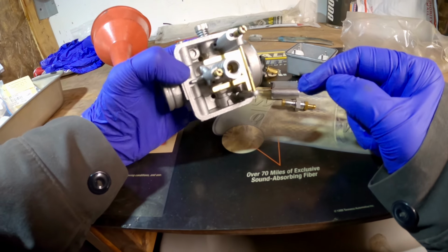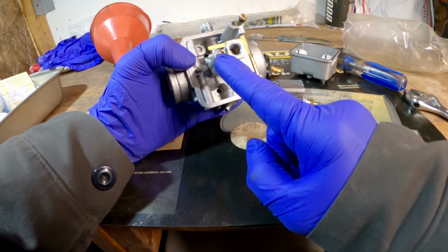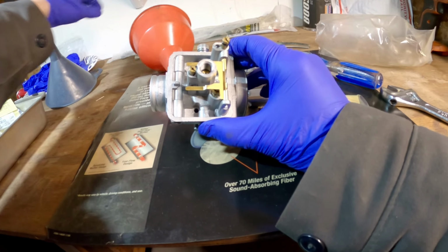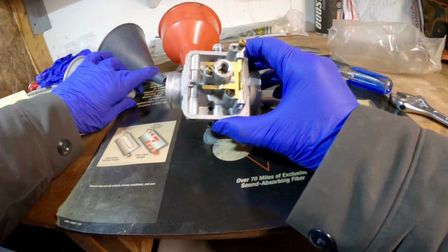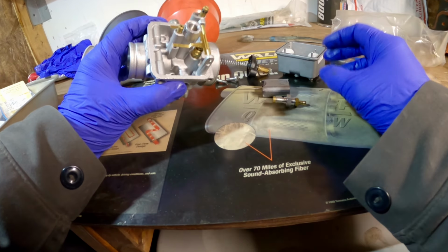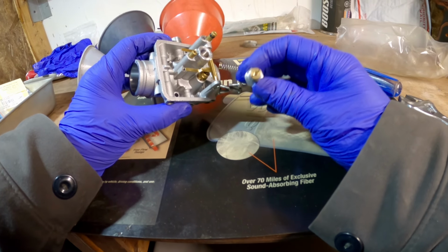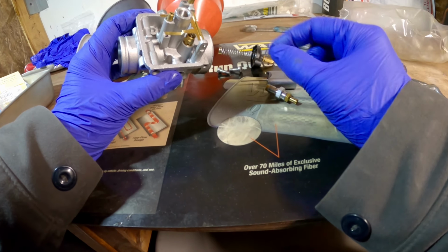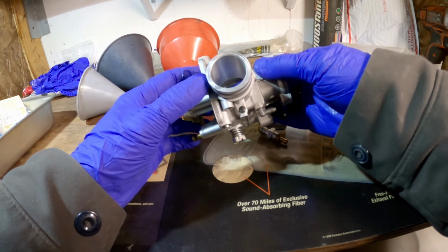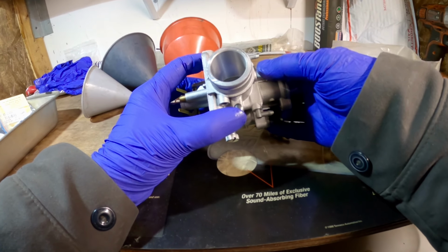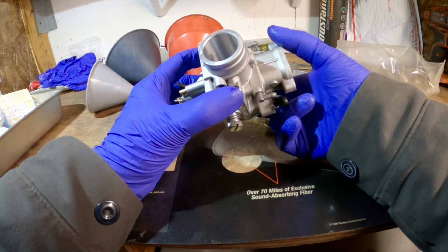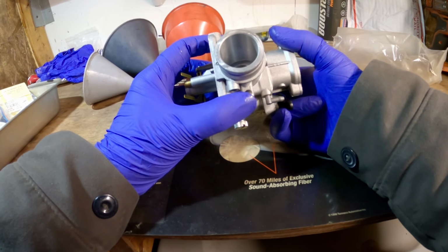So we got our pilot jet here. This pilot jet is going to have an effective area, just like these funnels here. So you can select different effective areas for that pilot, select different effective areas for the main jet. And down in here, you could see the needle jet, excuse me. This is the needle jet with a cutaway to create some vacuum and help with vaporization.